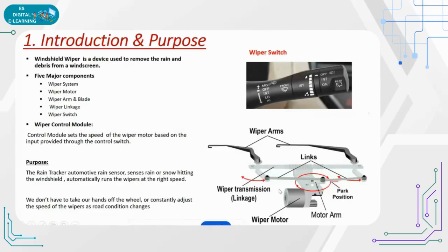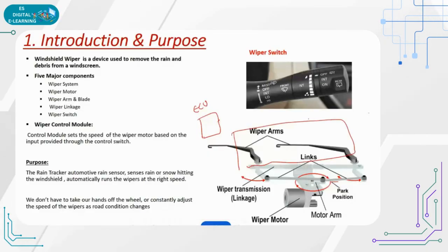Okay, for example, if you say here, this is a controller. Okay, imagine this is a body control module ECU, and imagine here you have the screen. Okay, so the water is dropping. Okay, the water raindrop has fallen here. So whenever it falls, there is a sensor. So the sensor will take that information, and it will pass the signal, analog input signal, to the ECU. Then what it will do, the ECU will process, and it will start rotating the motor.